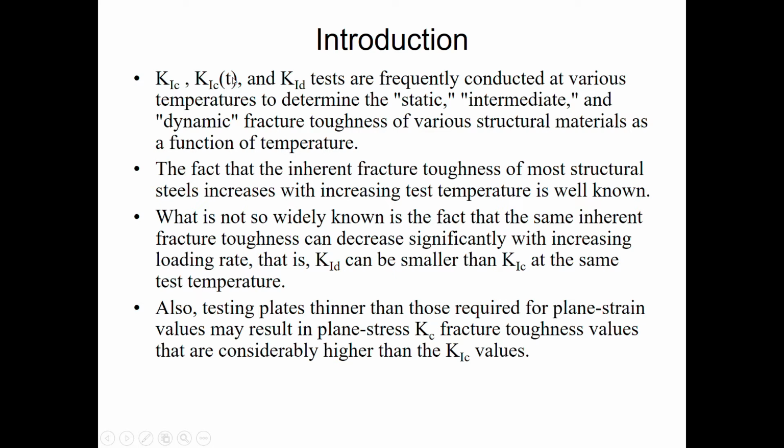K1C in bracket T, which is K1C as a function of time, and K1D tests are frequently conducted at various temperatures to determine the static, intermediate, and dynamic fracture toughness of various structural materials as a function of temperature. The fact that the inherent fracture toughness of most structural steels increases with increasing test temperature is well known.